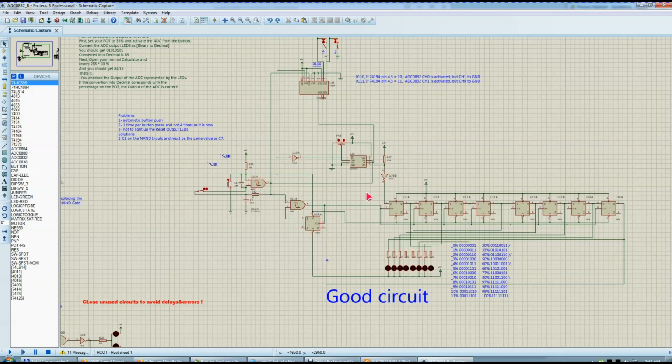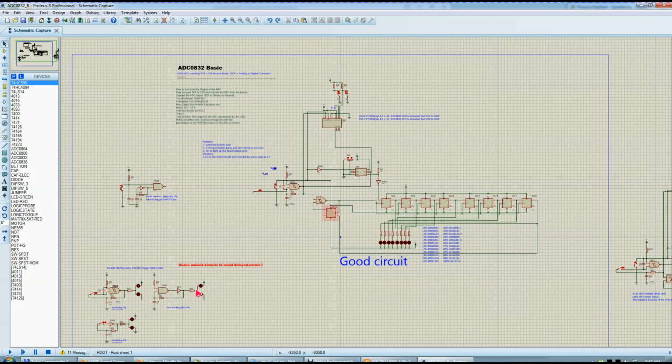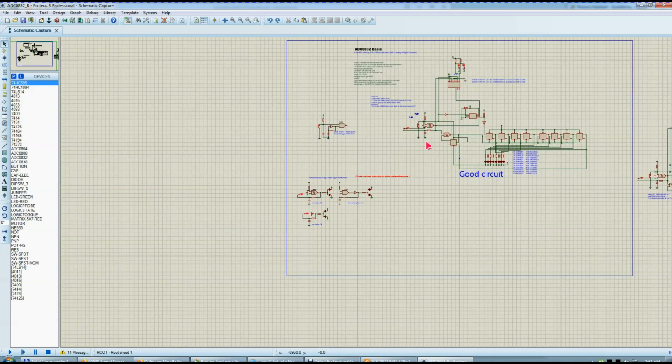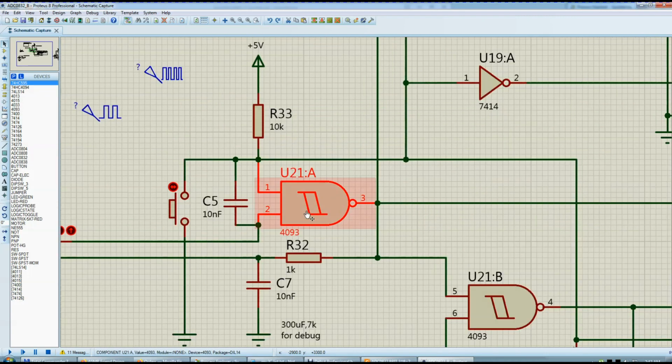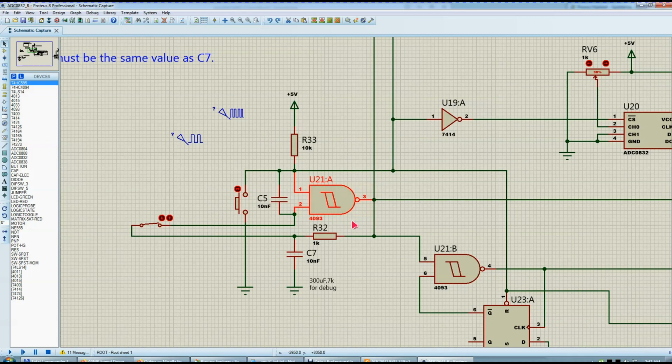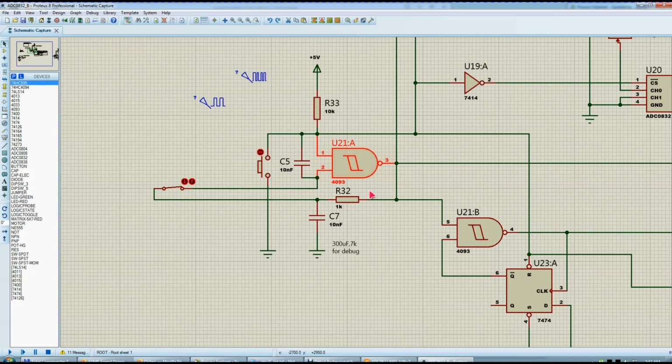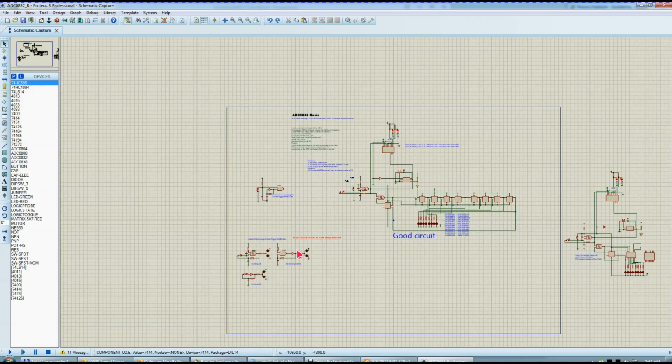So this is one important thing: the timing and the code, the clocking and the code to this chip is very, very important. Then we played around, and I told him I don't have this 4093 chip at all. This is also a very new thing for me, making a clock from a NAND gate. I'm not used to it, at least practically. What I practically use most of the time is the 555. But there are other ways of clocking, and this is a very interesting modality.